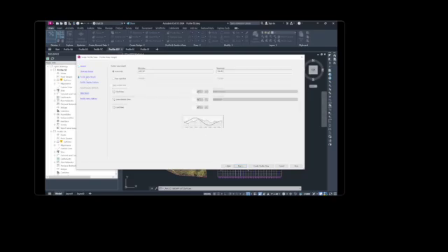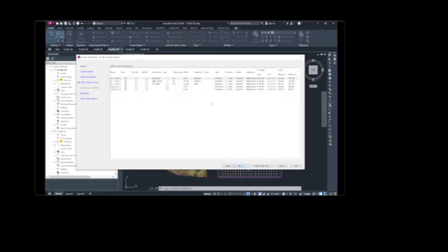On the left side of the wizard click Profile View Height, and then on the View Height page we're going to set some parameters: profile view height user specified, maximum 670, split profile view selected. Click next.